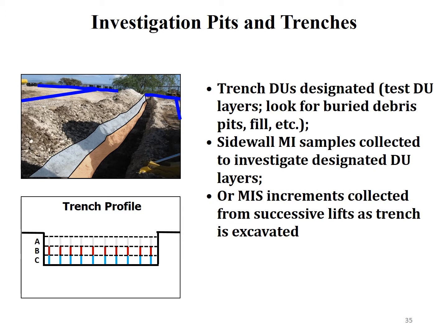Another approach is that you could actually use coring devices to sample a top layer down to a certain depth, and then as that depth lift is taken out, come back with your coring device and sample the next lift, and after that's removed, sample down. That's another technique that could be used.